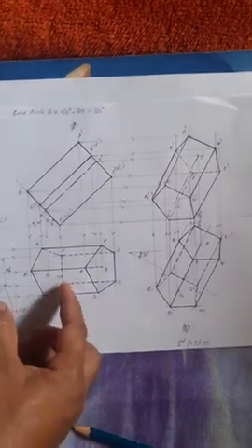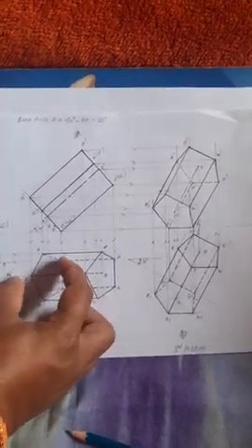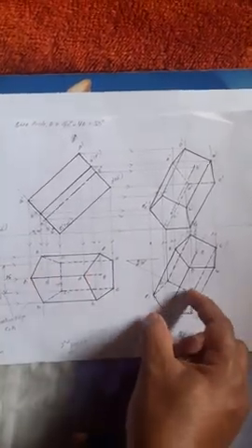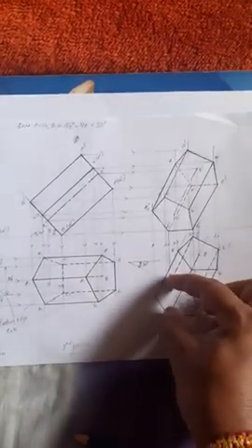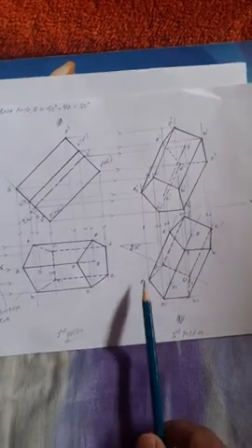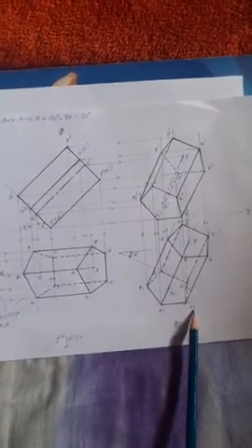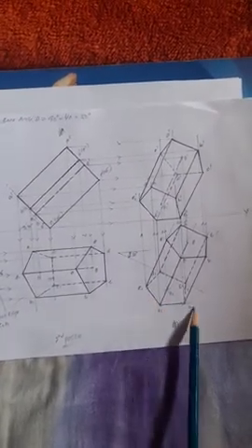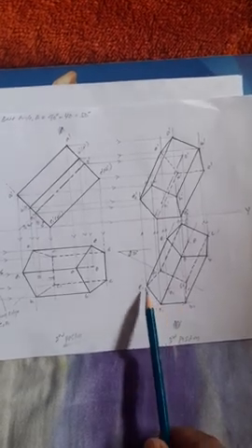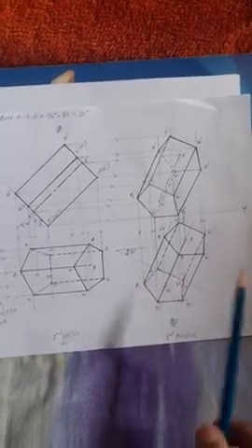Next we know C1 A1 is equal to D1 A1. Then from C1 draw an arc of radius C1 A1, and from D1 draw an arc of radius D1 A1. Now we'll get E1, A1, B1. Just mark these intersection points and name them, don't join them.